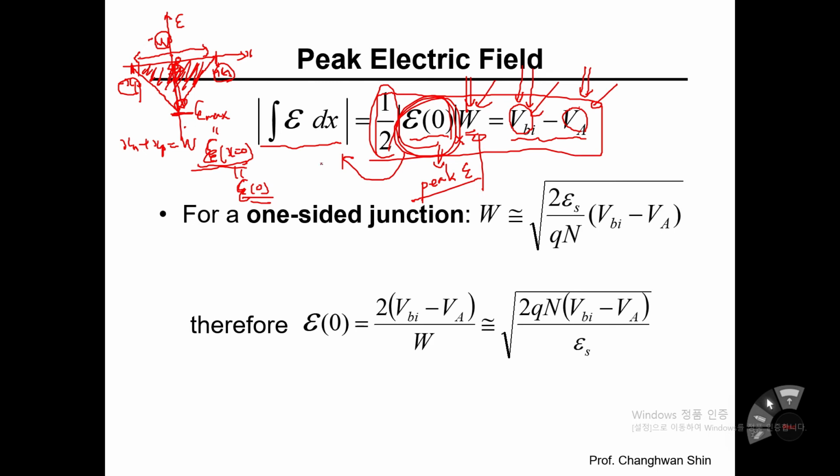All right. And the next topic is the one-sided PN junction diode. One-sided means, you know, a PN diode is given, and either side of the PN diode has been very heavily doped, such as P++ N, or PN++, like that. So either part of the PN junction diode has been very, very heavily doped or degenerately doped. We can call it a one-sided PN junction diode.